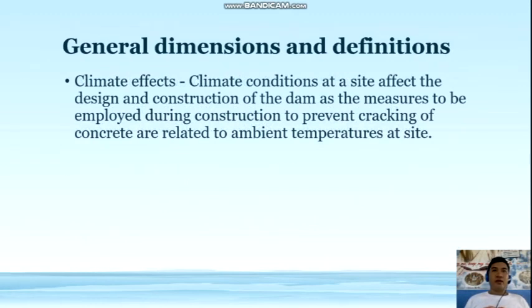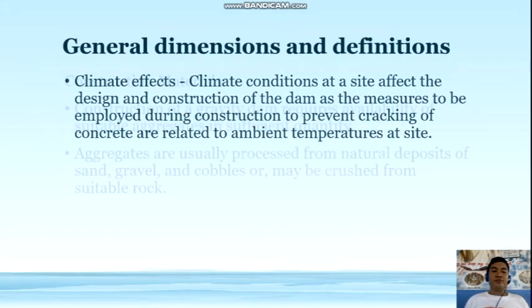Climate effects. Climate conditions at a site affect the design and construction of the dam, as the measures to be employed during construction to prevent cracking of concrete are related to ambient temperatures at site.